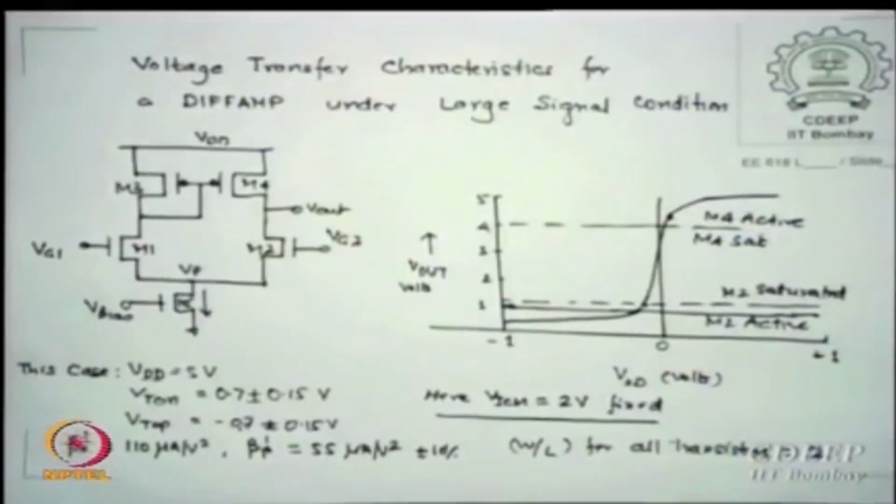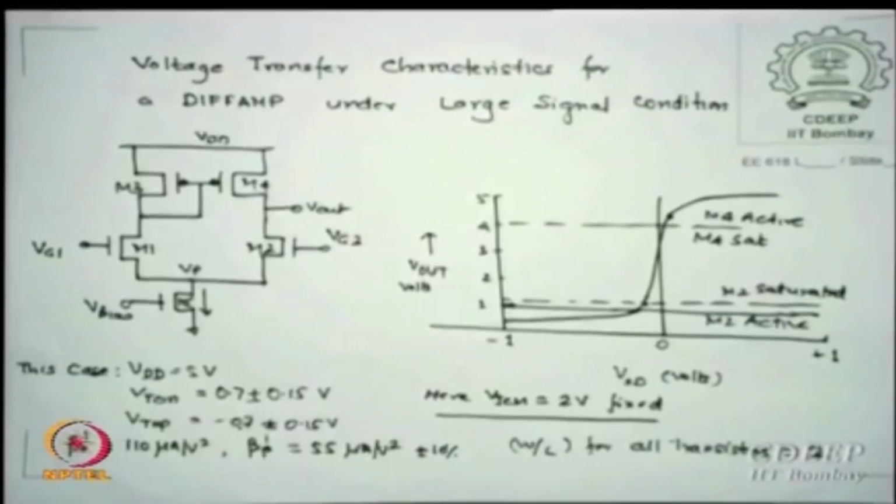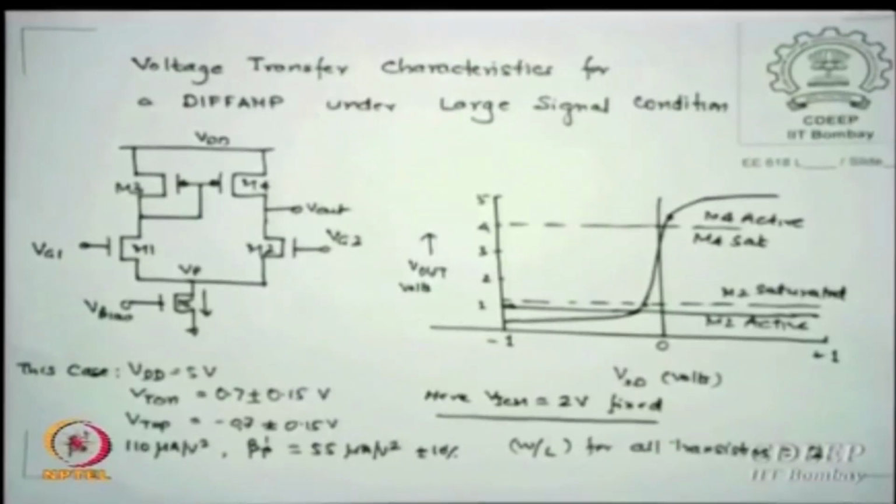There are of course Spectre or SPICE that do not allow so much easily, but there is a model card in SPICE which you can write yourself. So it is not that their default values are there and you have to only work with them, you can change your model parameters and still work on it if you use a model card of your own.